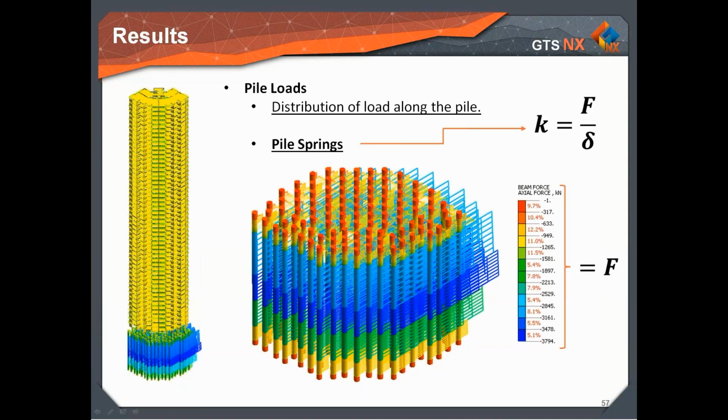This is a piled raft hypothesis. Values of pressure above the raft might be divided by the settlement in the same point. So this also might be sent to the structure team or exported to Midas Gen.